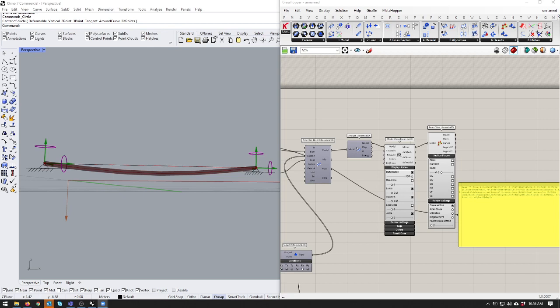meters. And it doesn't matter if you're drawing in millimeters or inches or anything. It's going to look at any unit that you draw and assume that it's a meter. So you've drawn a 500 meter beam, not a 500 millimeter beam. So number one, can you change your units to meters?